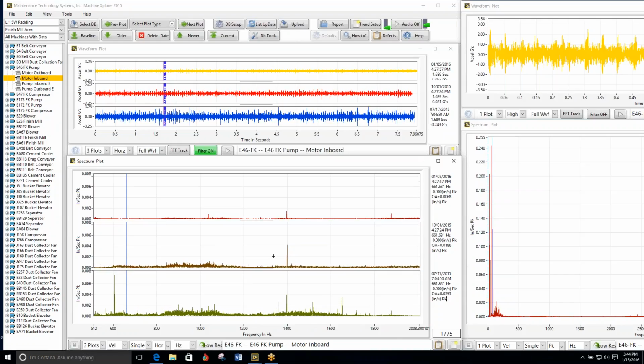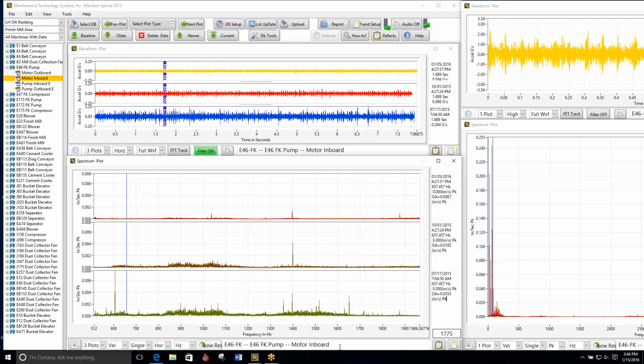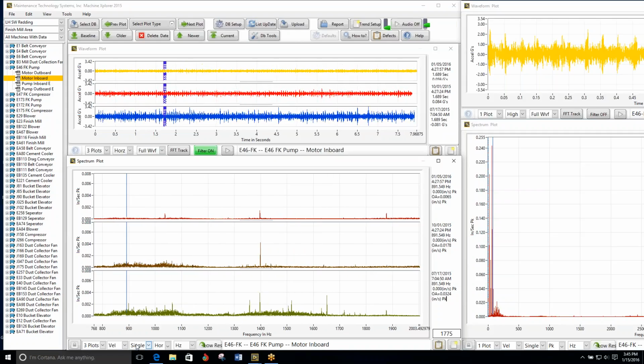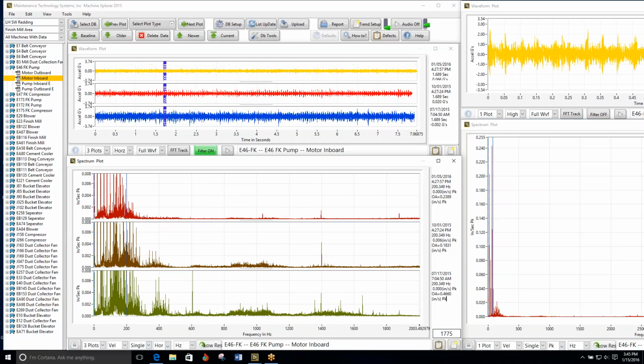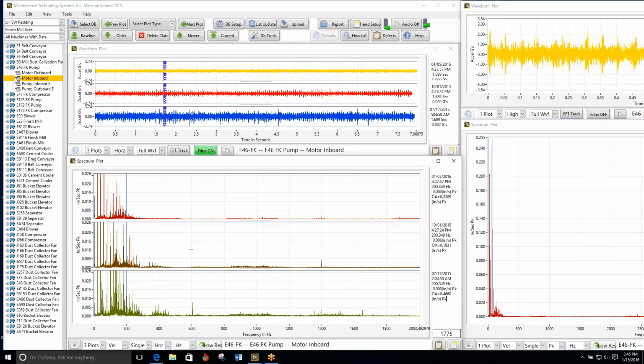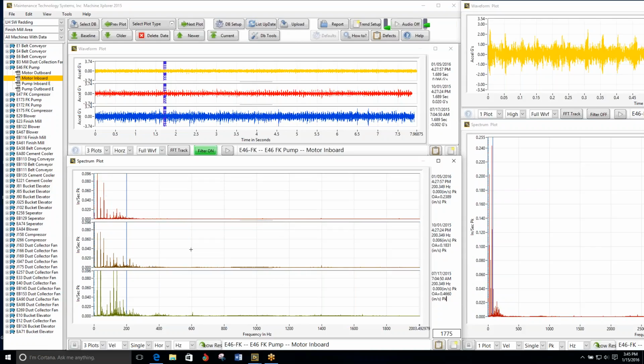I like that. Is that cool or what? Now, where did you do that at again, where the blue line is? Okay. This bottom portion of the spectrum, if I divide it in half, if I roll the mouse wheel on this side, it changes the Fmax number. If I go to the left half and roll the mouse wheel, it changes the Fmin number. If I come up on the plot, then the mouse wheel changes the amplitude of the plot. All right.